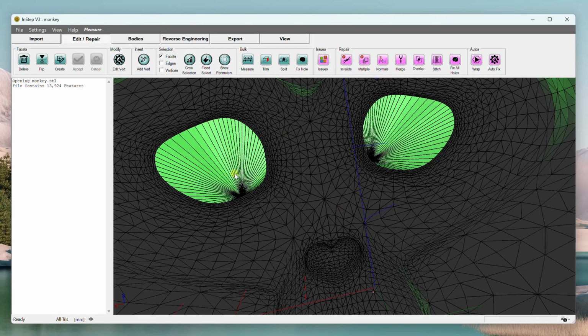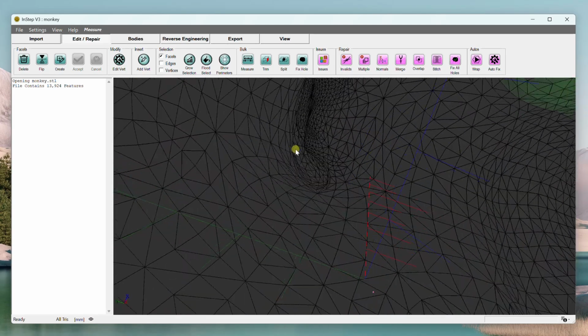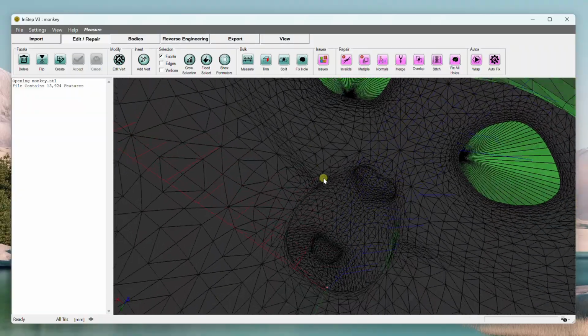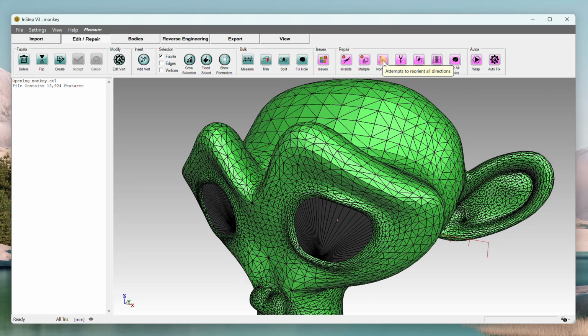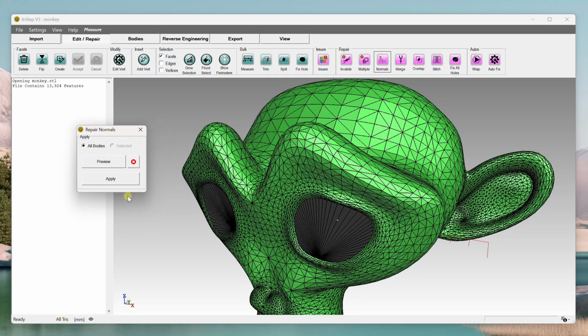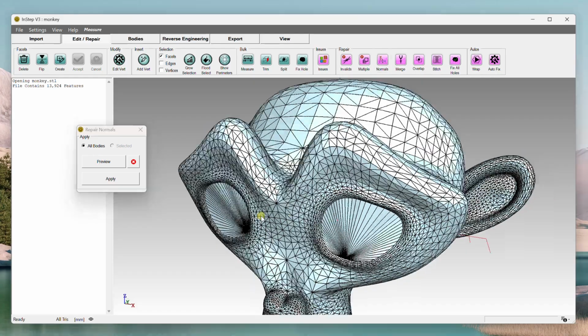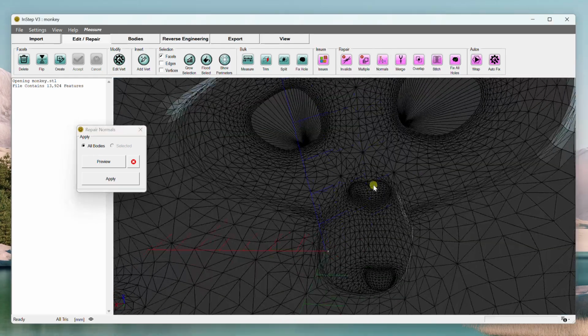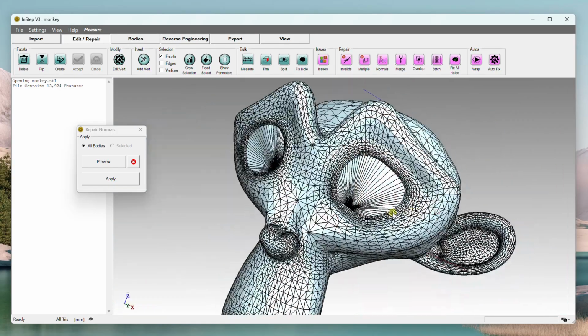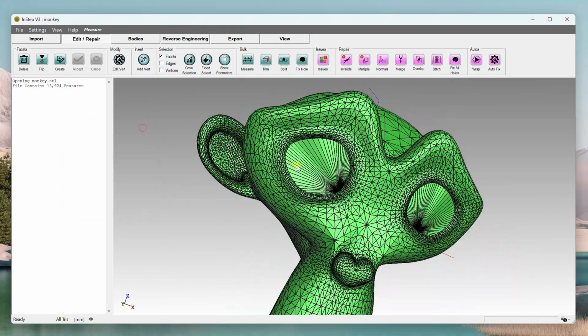And it's very important that these are oriented in the correct way, because the step file doesn't really know what to do with these if they're not oriented in the correct way. So normals should always be applied in such a way that they point outwards. We can go into the normals tool, and again, it's a very simple option. It automatically determines which direction all facets should point in. And if we click preview, it'll take just a second, updates it all, and we can see now that they're all oriented in the correct way. If we hit apply, we're left with a valid body again.